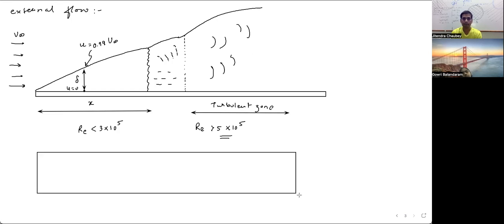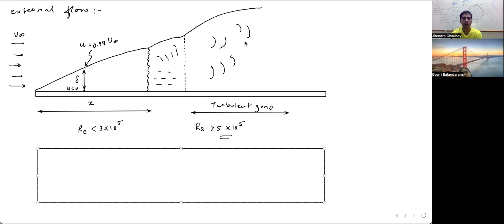If I draw a pipe, when the fluid enters the pipe, it has some initial velocity, the free stream velocity. When it comes in contact with the pipe, the fluid nearer to the surface will retard. The centermost will have max velocity, and some fluid adjacent to it will also have the same velocity, but the fluid near the pipe will have lesser velocity.